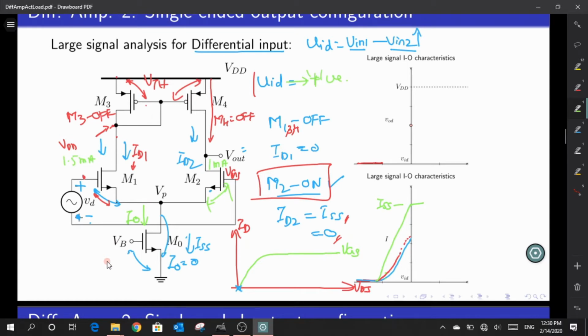You see, I know that the M4 is trying to receive a value of 1.5 milliamperes, but the bottom structure is not capable of accepting that particular current. So now what's supposed to be the drain and source of this M4 such that it can accept 1 milliampere? The point is that even though the transistor has enough VGS to draw a current of 1.5 milliamperes, the bottom structure is not capable of taking those 1.5 milliamperes. It is capable of taking only 1 milliampere out of it, okay?